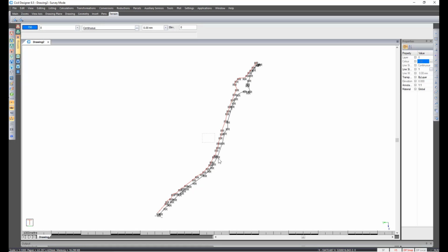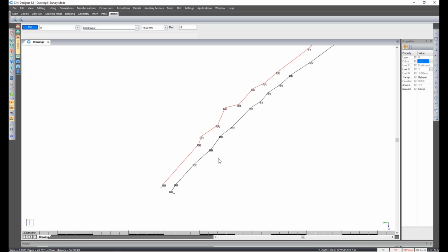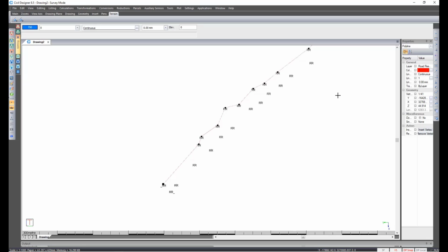So you can see we've got an additional red line. I'm going to press ZL on my keyboard. That line is now the polyline. I'm going to turn off my line model and select the polyline. So looking at our properties, we've got the polyline. As mentioned before, the objective is to go and put in road linear furniture that is draped on the ground.